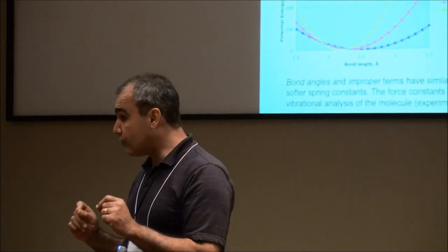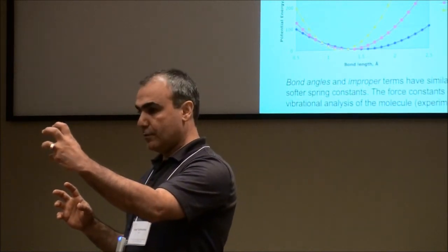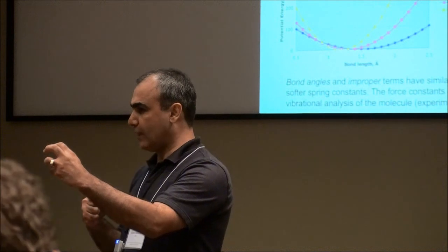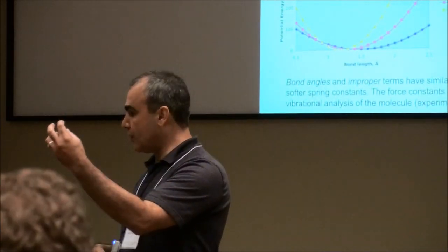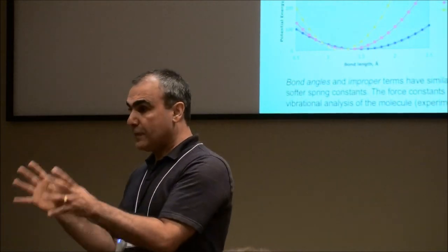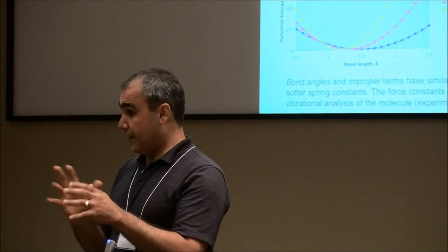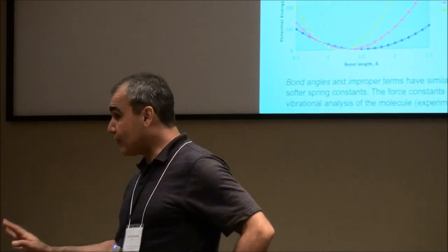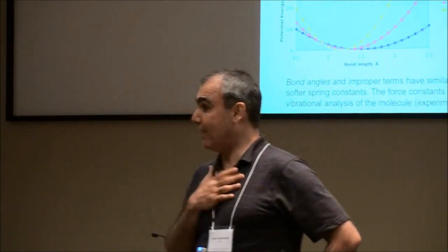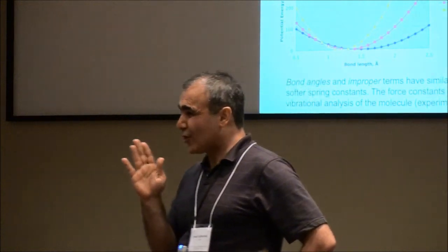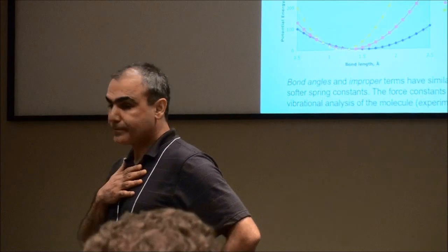You can even modify your force field to test. For example, let's say this hydrogen should be more positive in the presence of a negative charge. I know that. So I can artificially change the charge of that particular hydrogen and repeat my simulation and see if the phenomenon that I think I've discovered is still robust and is there. If that's the case, I say it's force field independent. What I see is real. It's an intrinsic behavior of this molecular system. It's not because my charge is slightly wrong. So you can test these things very efficiently as well.